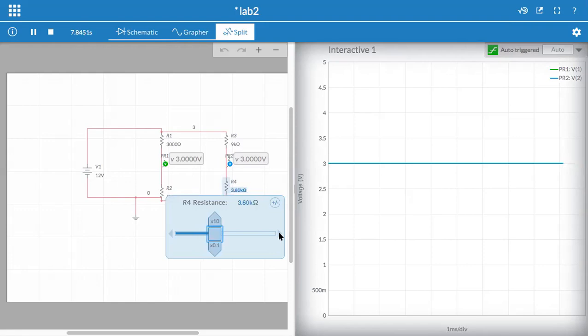What did you see? The blue voltage goes up, right? Right now, the blue voltage is almost 4.029. So now the blue voltage is much higher than the green. So what's the difference? The voltage difference will be 1. So now the output of this bridge will be 1 volt, because the output is the difference between the blue and the green. Right now, the difference between the blue and the green is 1. So the output of my bridge will be 1. That is if temperature increases.